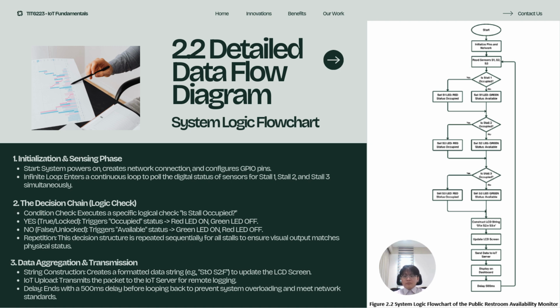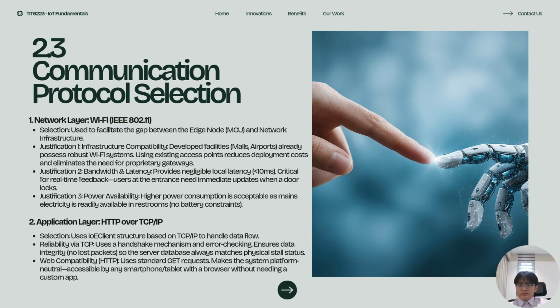So last, the loop ends with data aggregation and transmission. After determining the status of all stalls, the system creates a formatted data string. It uses this packet to update the text on the LCD screen and simultaneously transmit it to the IoT server for remote logging. Importantly, the flow ends with a 500 ms delay before looping back to the start. This is important because it prevents the microcontroller from overloading and ensures that our data transmission meets the network stability standards. So let us move on to section 2.3, communication protocol selection.